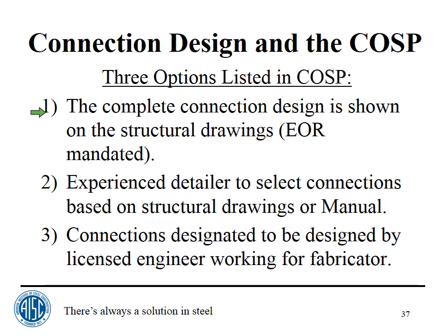These would be basically simple connections where there's no design per se, but rather just a table lookup kind of thing. And then there's three where the connections are designated to be designed by a licensed engineer working for the fabricator, either working directly for the fabricator or a third-party consultant that specializes in that kind of activity.